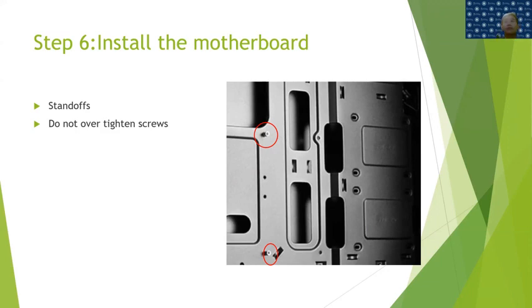Now it's very important that you don't over tighten them. Once you feel a moderate amount of resistance, that's where you should stop. Make sure it's not so under tightened that you can just move it around with your finger, but not over tightened to the point where you're trying as hard as you can to tighten it.